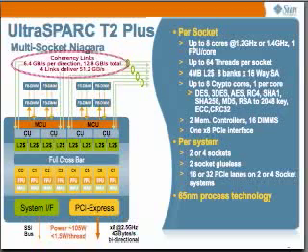multiple processors or sockets. On the coherence side, we have 4 links. Each link has 6.4 gigabytes per second per direction. It's bidirectional, so you have 12.8 gigabytes per second of coherence bandwidth per link, and there are 4 of those.